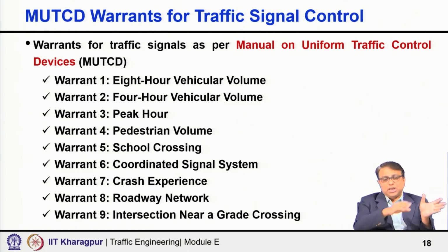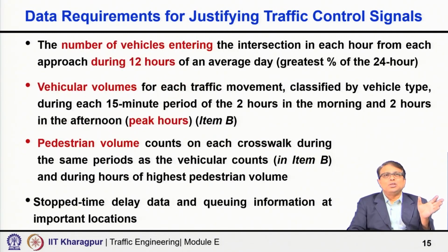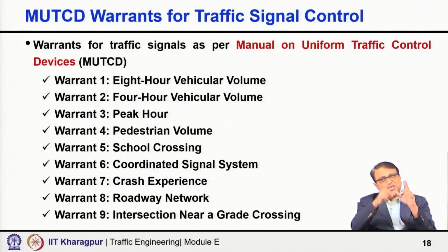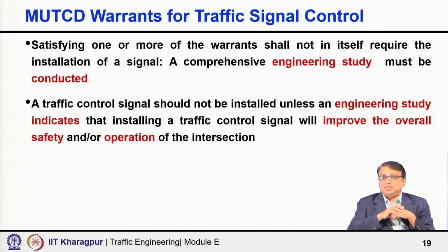All these data and studies are useful to get the necessary data so that these warrants can be checked. Before I close, one very important thing: remember that there are MUTCD warrants, but satisfying one or more warrants shall not in itself require the installation of a signal.